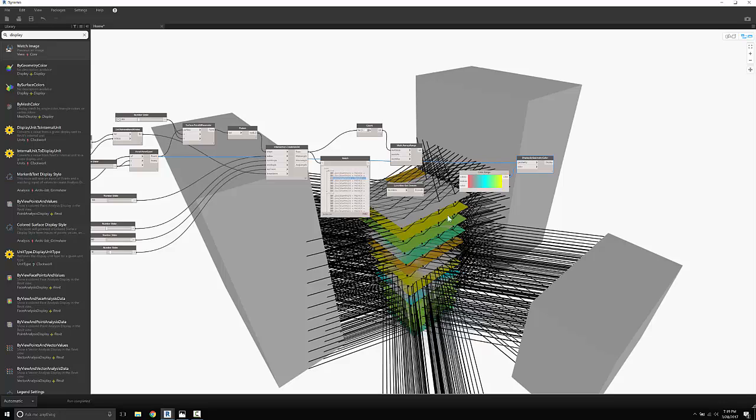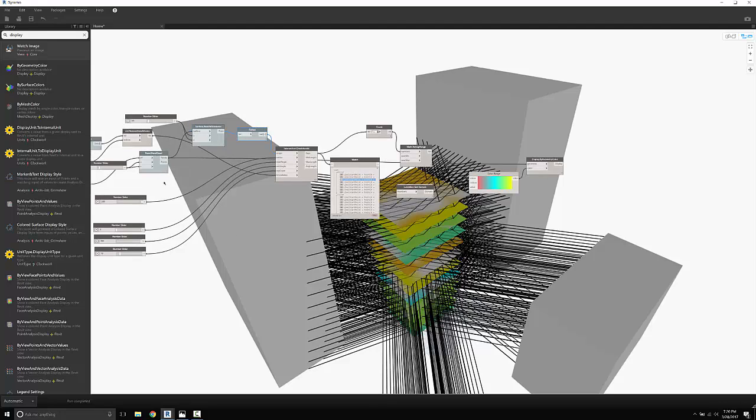Now, a lot of you were getting this on Monday, where you're getting grays and the colors are not kind of matching up the way that you would expect, especially with these grays over the top. You have to make sure you understand that each time you put another component in, especially once you get after this panel quad, you're making copies of that geometry, and all that geometry is sitting over the top here, and it includes the view. So I need to go through and turn the preview off on all these components, and once I get it cleaned up, I need to turn maybe these original element faces off.